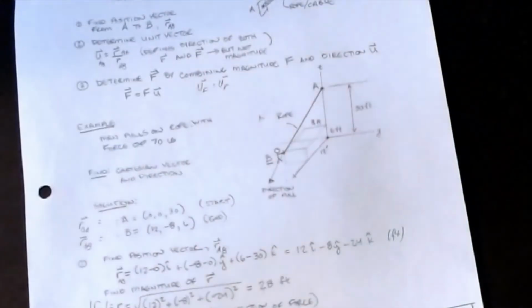So that will lead us into some properties of force vectors. A force vector is also known as a sliding vector, meaning that anywhere along its line of action, I can relocate it. As long as I stay on its line, it can move up and down, and that's what also allows me to move these unit vectors around, as they share the same line of action. But again, I don't want to diverge too much, but we'll get into that in the coming lessons.